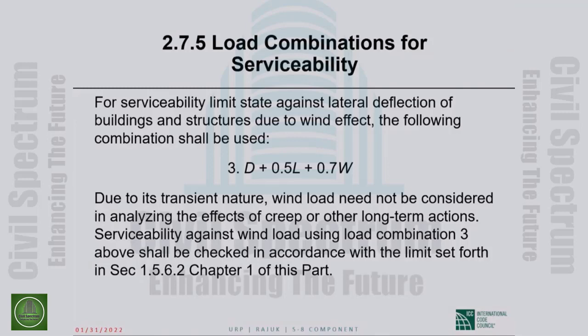In cases where, because you have a distinct lack of symmetry, dead and live loads may cause sideways deflection, you will take the short-term deflections. You will not worry about long-term deflections. This is what we are saying. Serviceability against wind using load combination 3 above shall be checked in accordance with limits set forth. We will go back to the table.